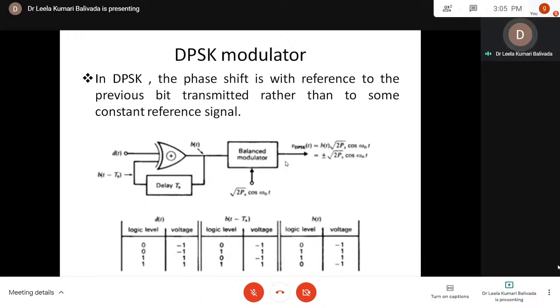To eliminate the need for phase synchronization of the receiver with PSK, we may incorporate this differential encoding. In differential encoding, we encode the digital information contents of binary data in terms of signal transitions. So symbol 0 is used to represent no transition in a given binary sequence with respect to the previously encoded information, and symbol 1 is used to represent a transition.